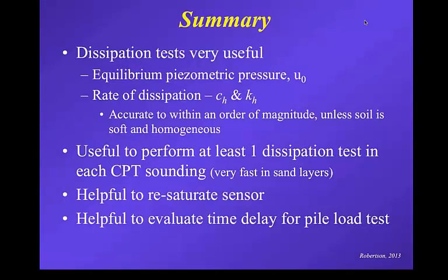First question, is it better to reach T90 or T80 in order to obtain a more accurate CH, or do they give similar values? Good question. The answer is it depends on how closely the theory matches the measured. I didn't show it, but a new feature that we're adding into CPTu is a curve fitting feature. Once you've done your interpretation, there's a little button where you can add the curve fitting.